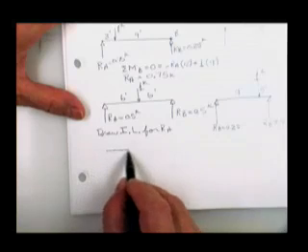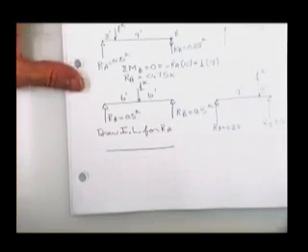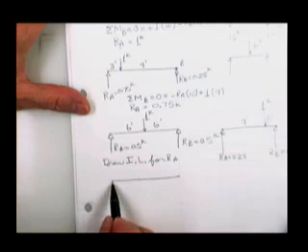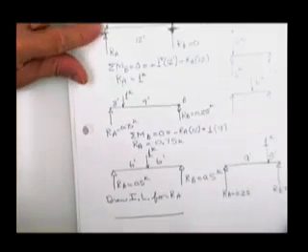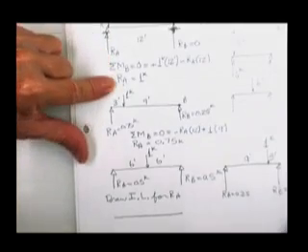Here is an influence line for the reaction at A. An influence line gives you the magnitude of the item you're looking for when the load is located at a given point. So when the 1 kip load is here, the reaction at A is a 1.